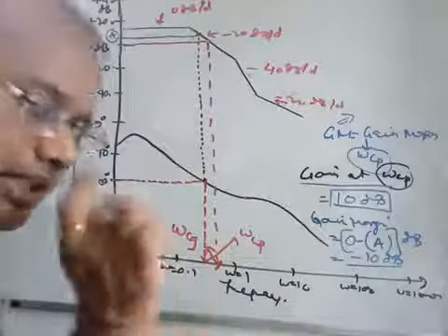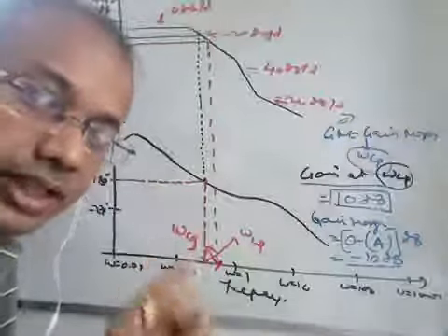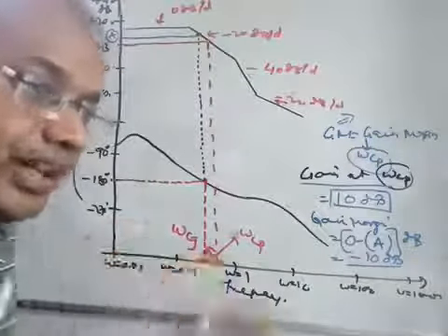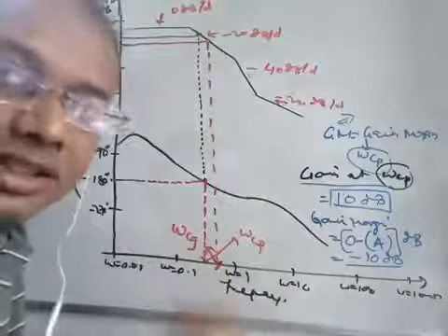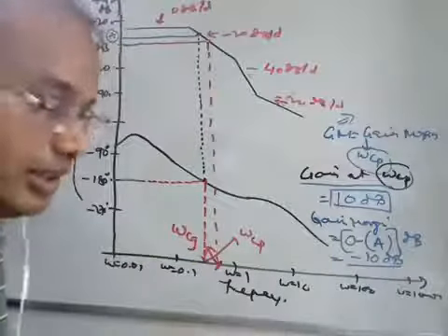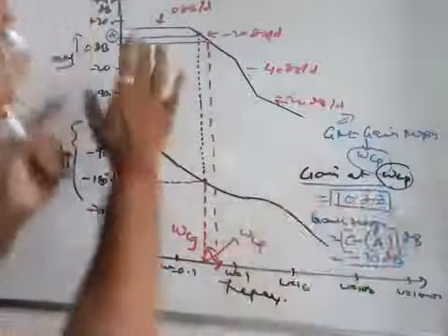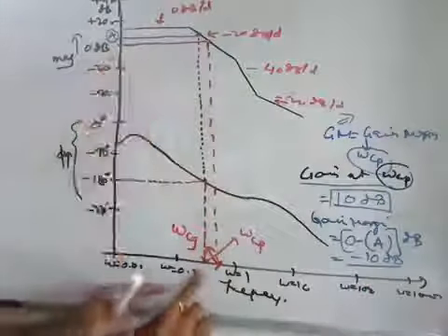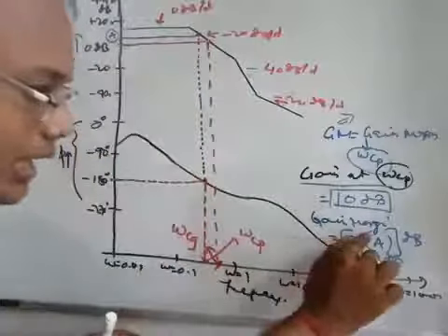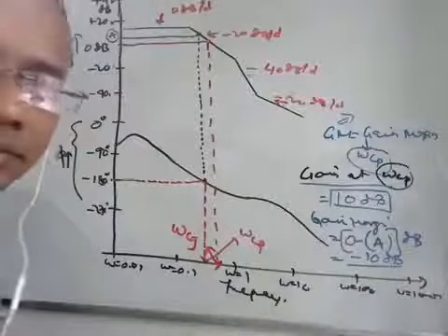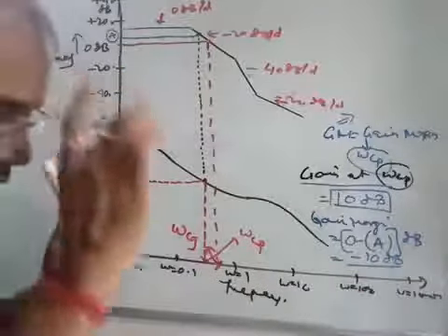So minus 10 dB. That means the additional gain margin is minus 10 dB. So with minus 10 dB additional gain you can modify the system such that the system gain becomes 0 dB. 0 dB is the standard gain of the system, right? That is the standard for stability analysis. So you calculate the gain at omega Cp, and once you calculate this value 10, the gain margin is equal to minus 10 dB. So that is the concept of gain margin.